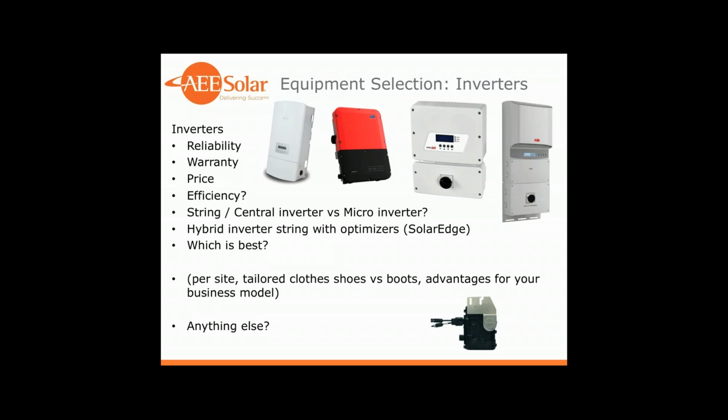And then for those job sites where you have a broader, wider open roof, well, you really should go with a string, or sometimes they call it a central inverter. You should go with one of those instead when you can, because they tend to deliver a better production per cost value, and that might allow you to get the sale, or even allow you to put some more solar modules on that roof for the same price.